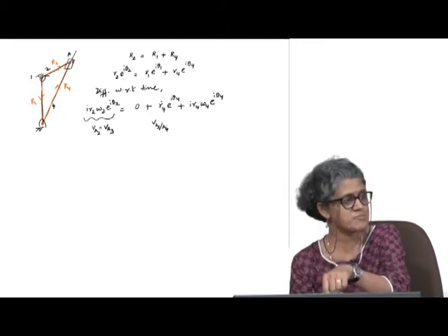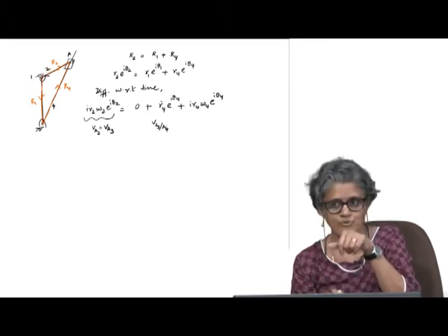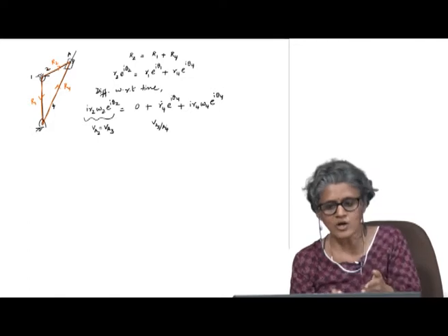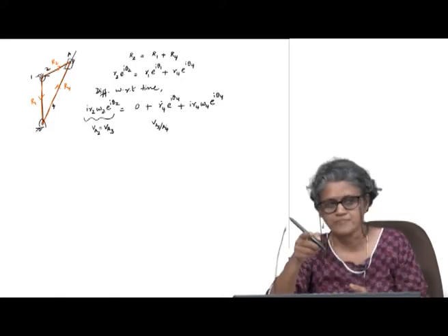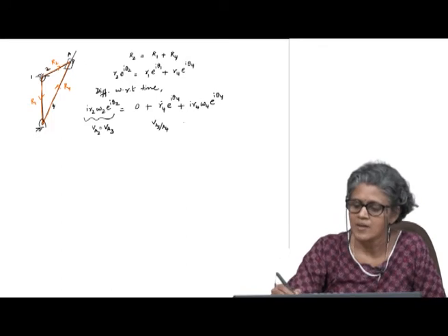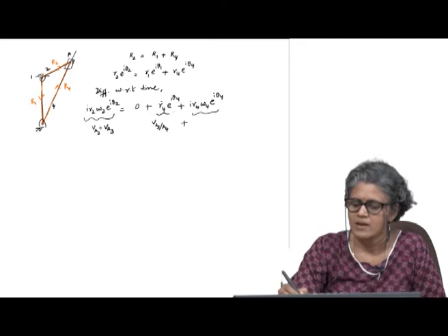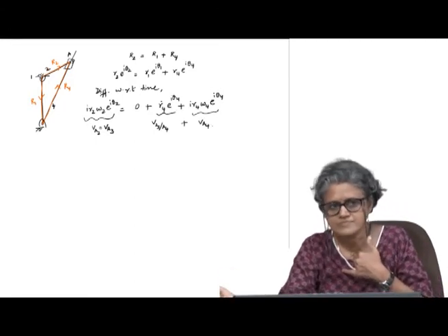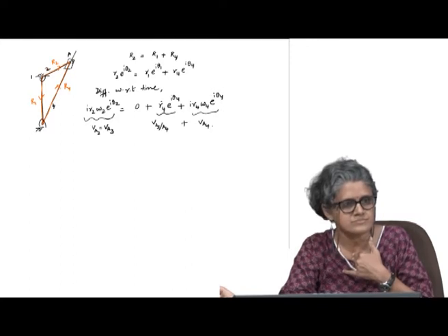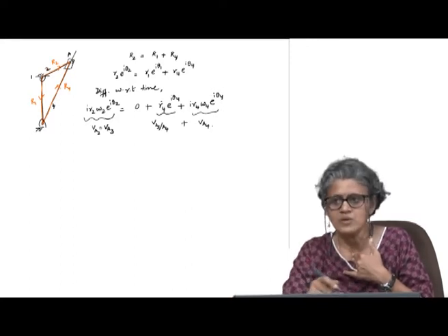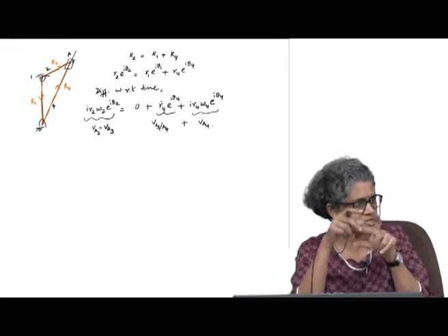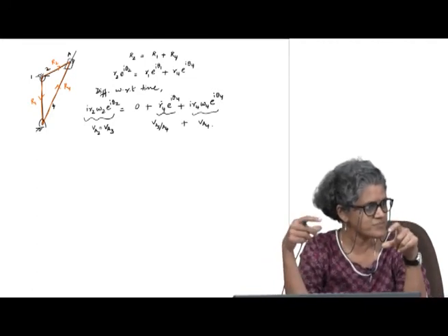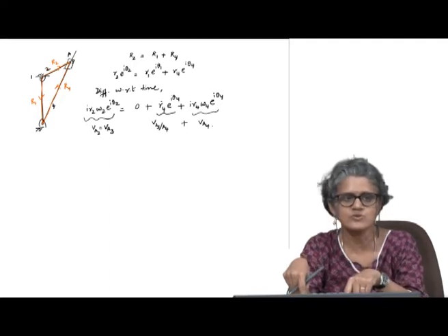So, this is your slip velocity R4 dot, and it is along the link 4, plus this velocity here is the velocity of A on body 4. Remember we used coincident points to set up that vector equation earlier. It follows directly from the loop closure equation.